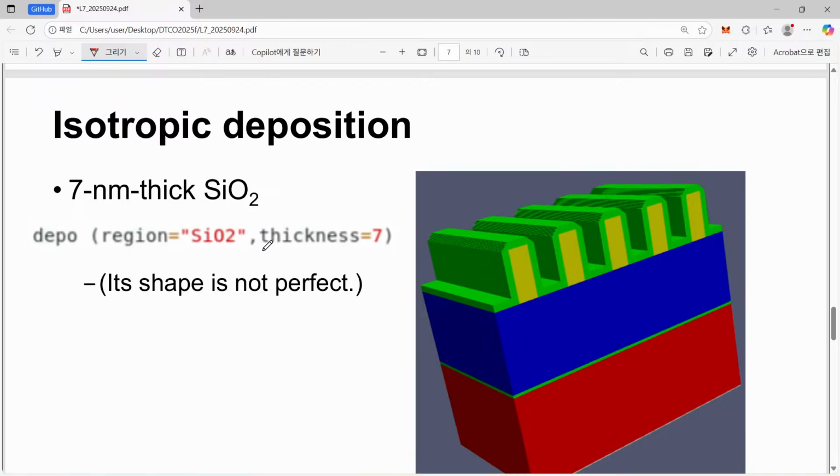Here we deposit a certain amount of silicon dioxide. Please note that once again, this is silicon nitride, and we intentionally use a different material, assuming that we can find a good etchant that can distinguish silicon dioxide and silicon nitride. A certain etchant can selectively etch silicon dioxide quite well, but does not etch silicon nitride at all, or with quite a low etch rate.